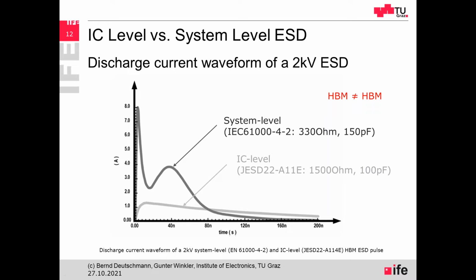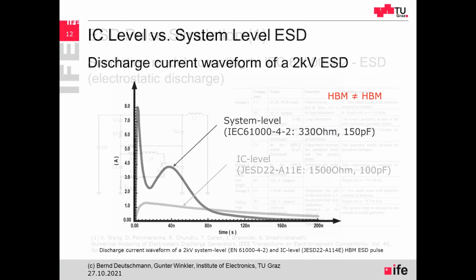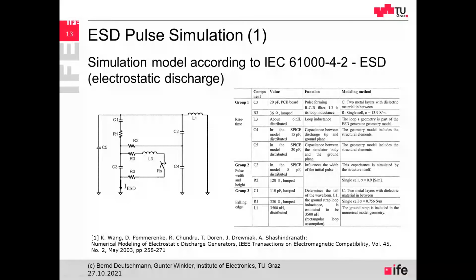And at the system level, we are testing the whole electronic system, not just for destruction, but also for any kind of malfunction. For example, if the system gets a reset or if it's working properly within a certain tolerance range. So very often for the development of electronic systems, it's very important to pre-estimate if your electronic system will survive this ESD testing or not.